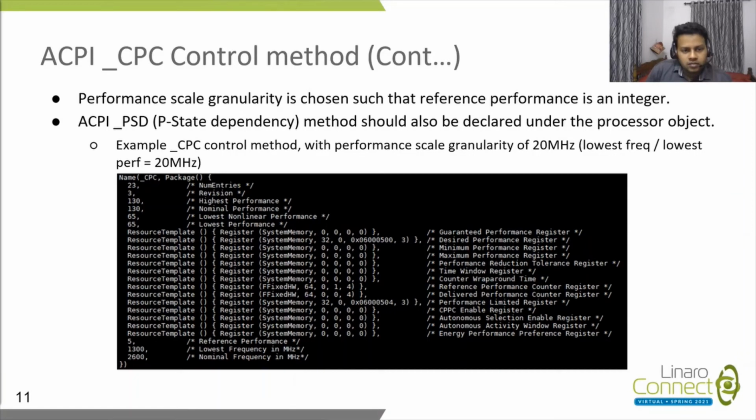And also the highest performance and the nominal performance should be exposed as integer values, and the desired performance register is exposed as the system memory, and the reference performance counter and the delivered performance counter are configured as the fixed hardware.